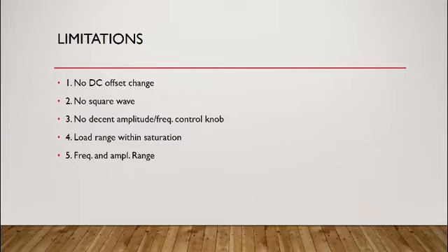The fourth thing is there is a load range within the saturation, because all the op-amps cannot produce an output higher than the power rail. So there's a limitation of how big the current can be driven and how big the load can be.